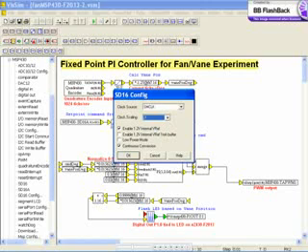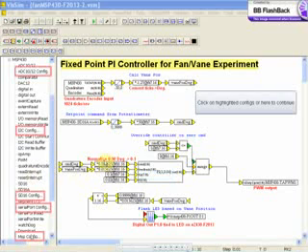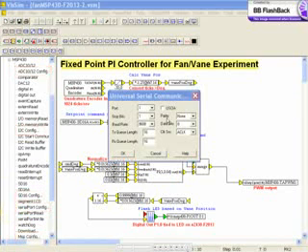The Sigma Delta converter will shut down in low power mode. It is started back up when a conversion is required. In single mode, the channel is converted once per activation. In continuous mode, the channel is converted continuously. Press OK to return to the main session.